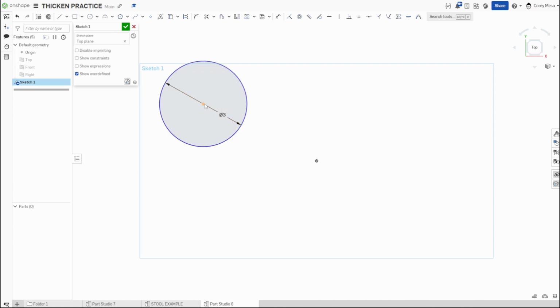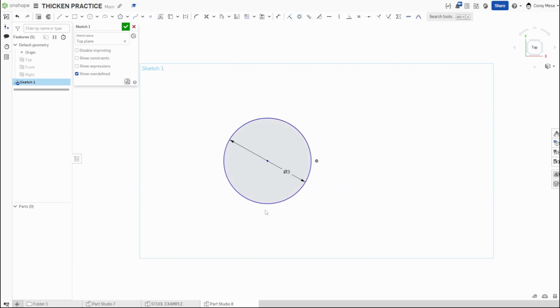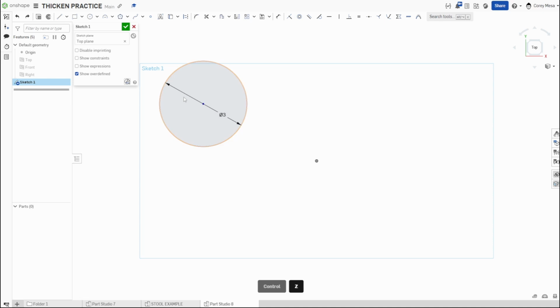So one of the things he was saying, he maybe clicked the two points and he said horizontal. Well, that's cool. It's now locked in place, but it could be anywhere along this horizontal axis, that x-axis, okay? We'll undo it. He did the same thing for vertical. He said, I tried that and it didn't do anything. It knows it's locked on that Y, but what's going on?